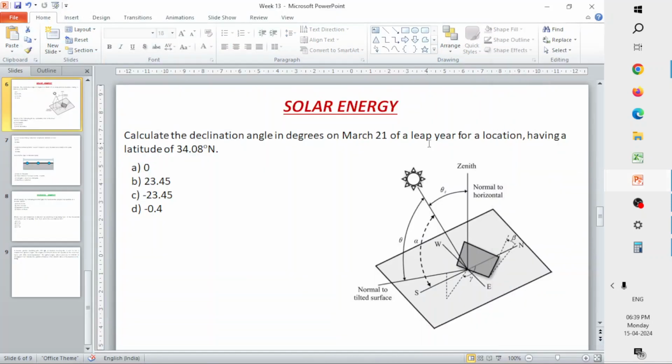That will be at the maximum power. So you are supposed to calculate that. We can express Cp as the actual power available in the rotor to the maximum power available in the rotor, right? So that Cp at that maximum power is what is called the peak power coefficient.